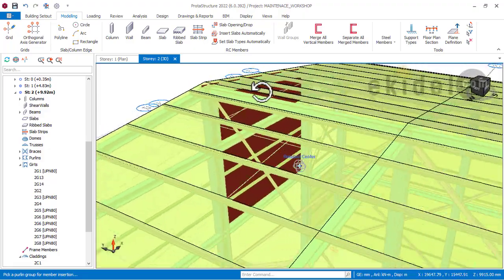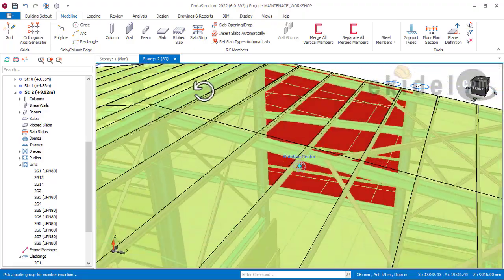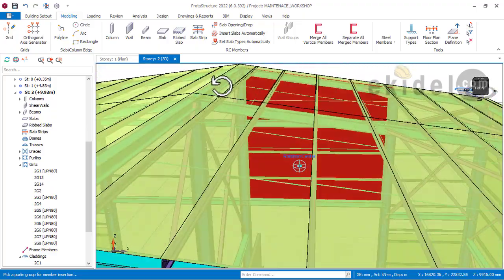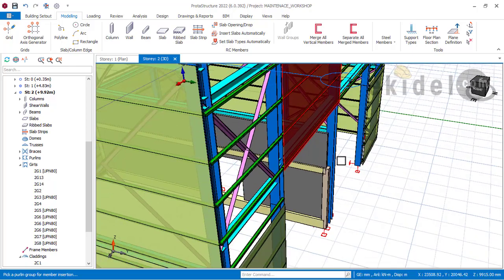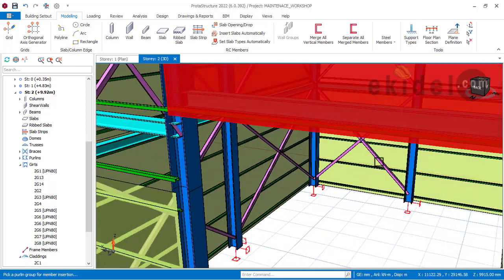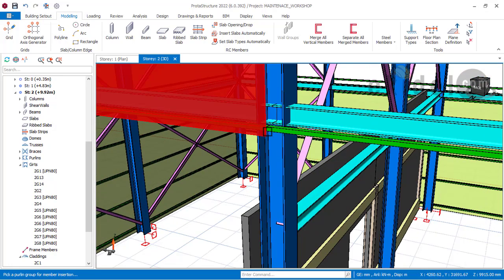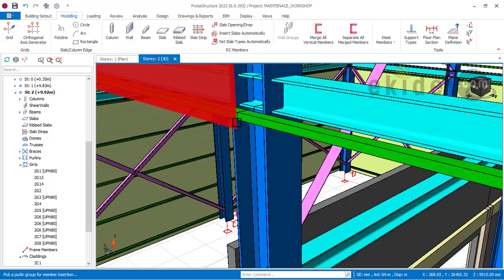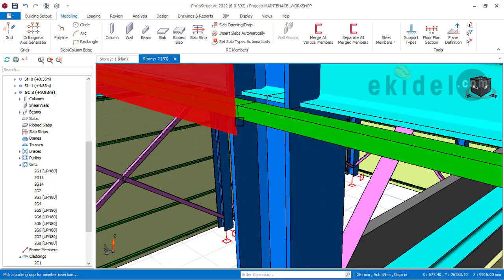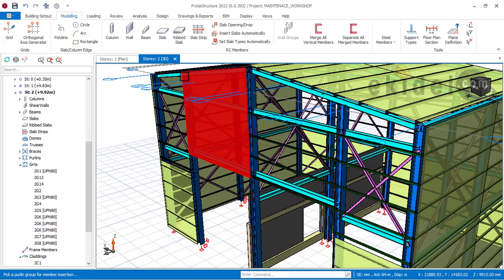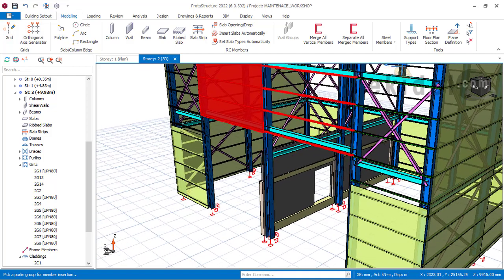If I view from this point, you can see that they are being sloped based on the beam sloping. Also on this entrance side, you can see that this cladding now stops directly at this side pole line, just giving a little allowance of at least 50. Now if you didn't put in that elevation, this is what you're going to get. You will get something like this.